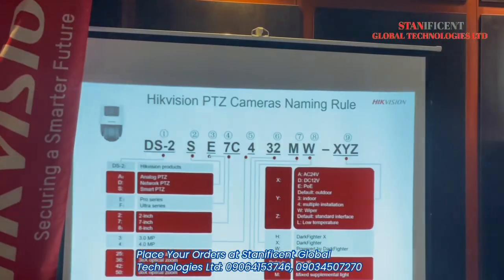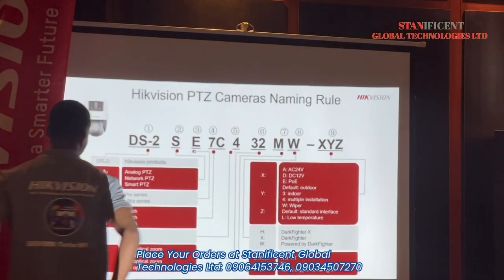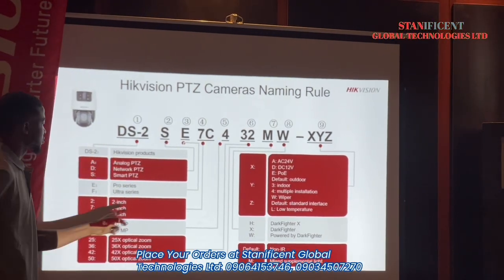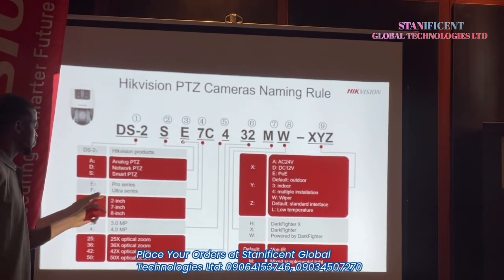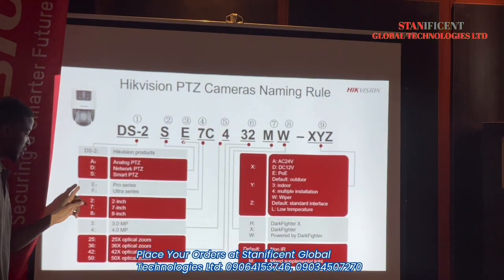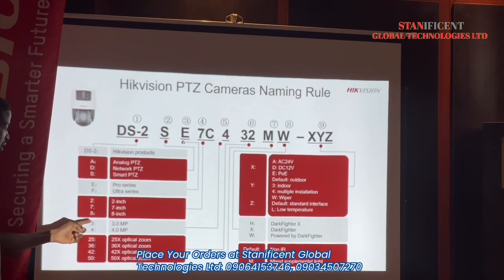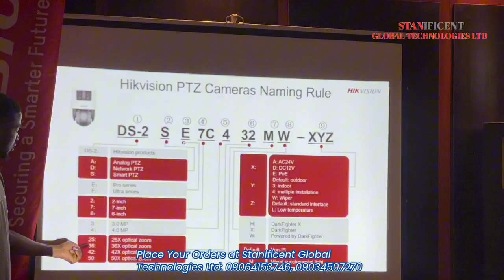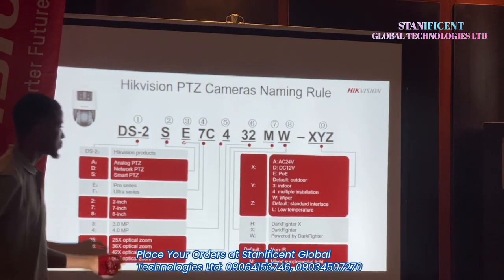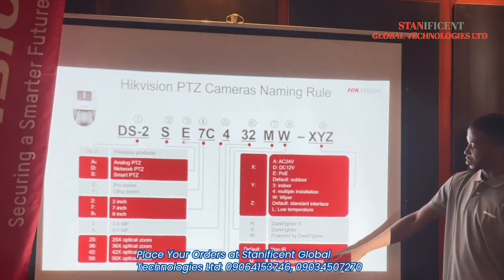Hikvision PTZ camera, walking us through the naming rule again. So DS2, front-end product. S stands for Smart PTZ. EF, E for Pro Series, F for Ultra Series. Then the inches of the camera, 2, 7, and 8. The MP, 3 and 4. The optical zoom is 25 times, 36, 42, and 50. And then we have the IR, non-IR, or mixed supplement light.